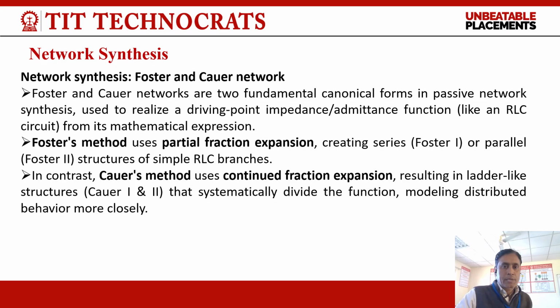Foster's method uses a partial fraction expansion creating series or parallel structures of simple RLC branches. In contrast, Cauer methods use continued fraction expansion resulting in ladder-like structures, Cauer 1 or Cauer 2, that systematically divide the function, modeling distributed behavior more closely.